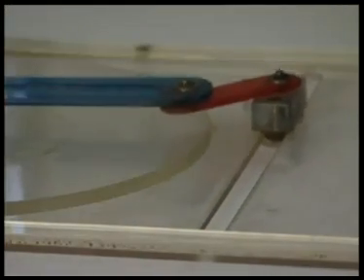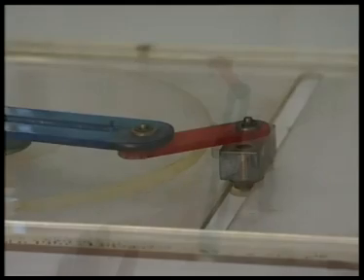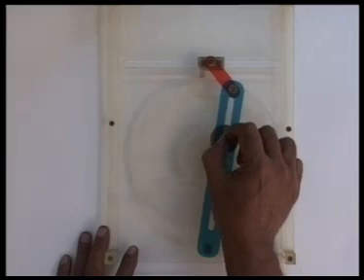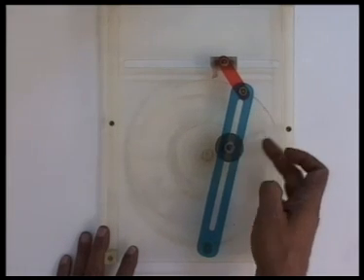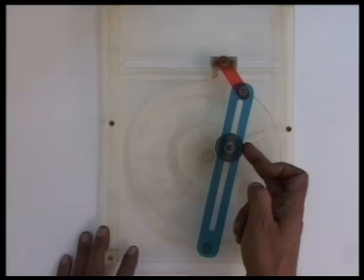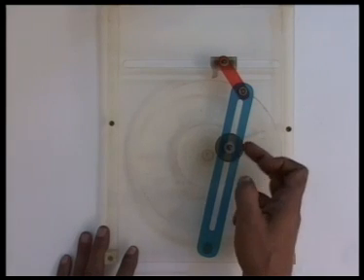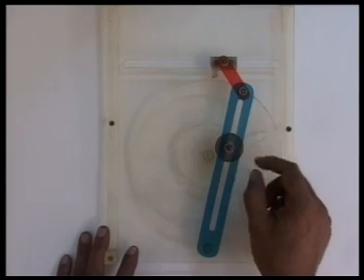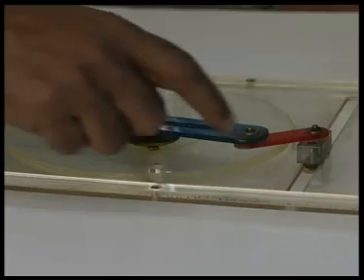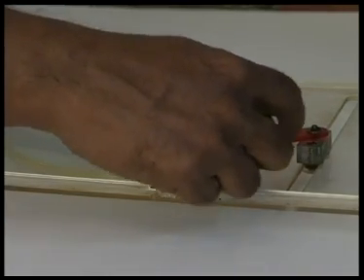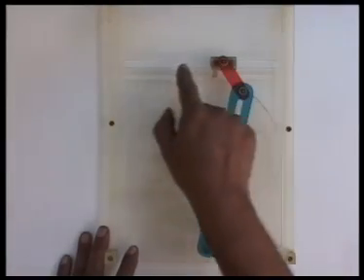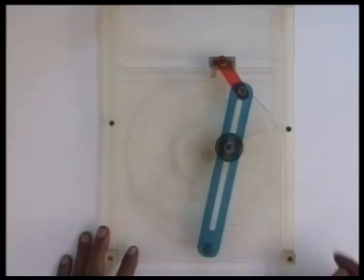This is the slotted lever quick return mechanism used in shaping machines. In this mechanism, there are 6 links. One is this rotating link, that is link number 2, fixed link is link number 1. This is link number 3, this circular block, which is hinged to body 2 at this point. And this is link number 4, the slotted lever. This is link number 5, and this tool holder or the tool is the link number 6, which has a prismatic pair in the body number 1.